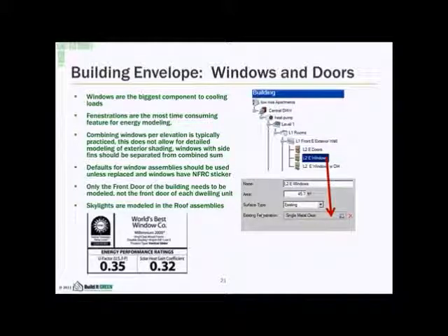So with older buildings, you're going to have to default to the vintage, and EnergyPro has the assemblies already built into the tree. So when you click in the existing fenestration, you'll get a list of some of the defaults for single metal, non-metal, double metal, and non-metal, and if it has a tint or not.